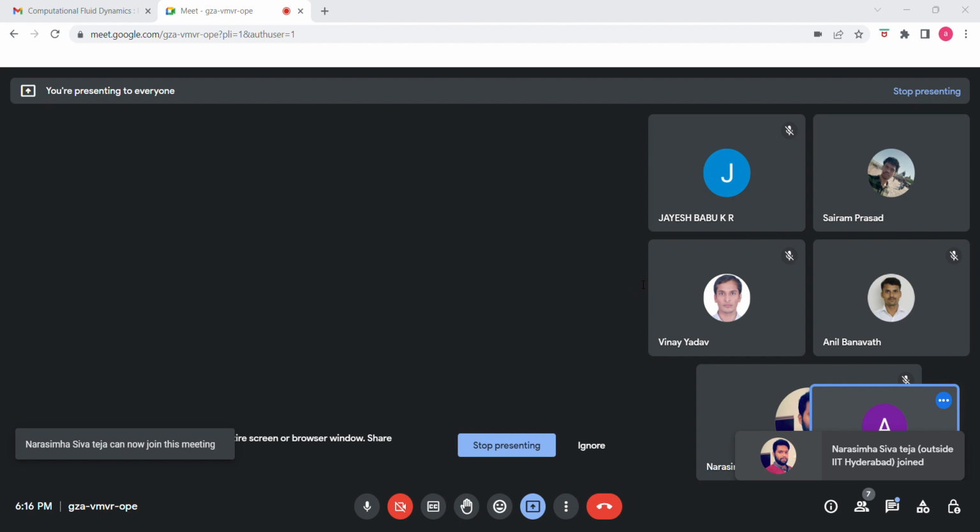So if we are to discretize this equation, in general we can write u i plus 1, j minus 2 u i, j plus u i minus 1, j, if we are moving in the x direction, with the whole thing divided by delta x squared. In a similar way, for discretizing in y, for the second derivative of u with respect to y, here j will change rather than i.